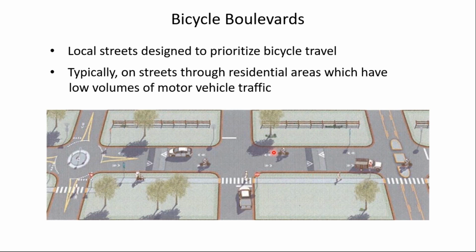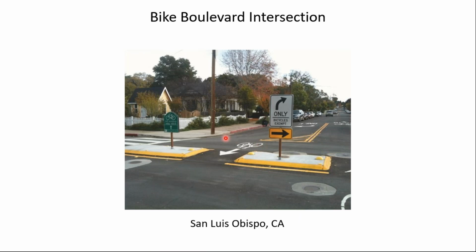But there might be issues with roundabouts, for example, or I should say the residential area traffic circles, with some special instructions for plowing. And there may be a need for some additional work. This may be manual activity, because if the streets are plowed, there might be windrows of snow. And so you might need, I don't know, maybe a skid steer or just manual labor to keep these openings in the median barrier clear. So yes, it would involve some extra instruction or extra activity, I guess. Good question.